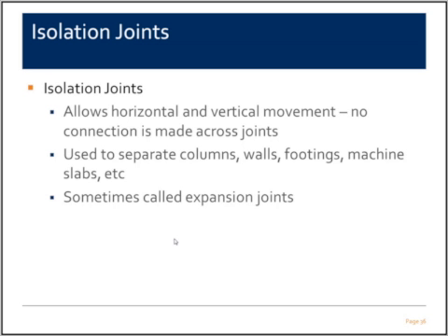Sometimes we'll see the isolation joints called expansion joints. I commonly, in slab-on-ground construction, call them isolation joints. We typically don't see much expansion in slab-on-ground construction, with exception of few special cases.